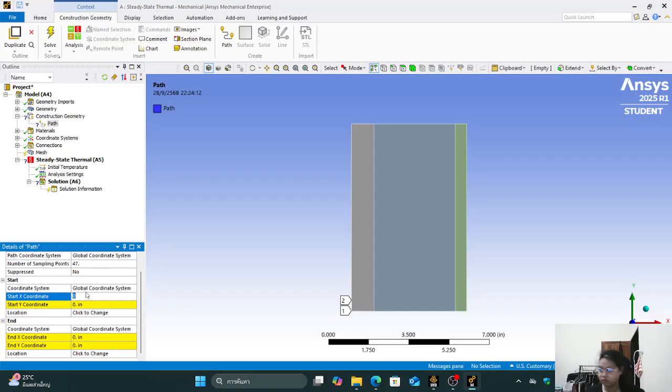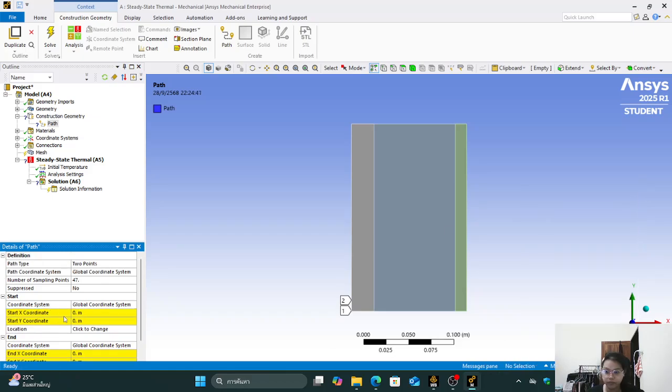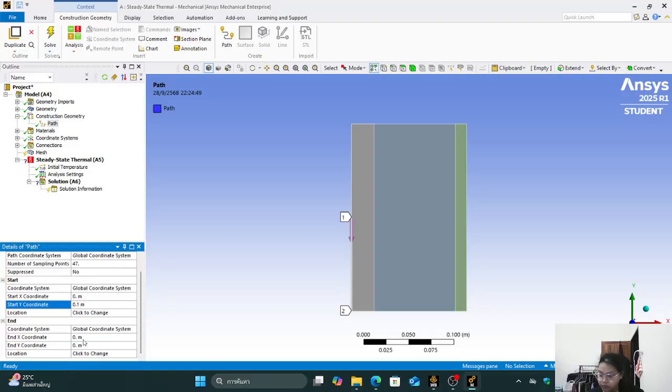So I want to start the first point from here. The geometry was created in centimeters, but now the standard units here you can see are meters. So I want to continue with these standard units. For that, the y coordinate will become, so the total height is 20 centimeters, so it will be 1. So that one is being moved there, and now we need to move 2 by putting this coordinate, which is 0.5, sorry, 0.1.